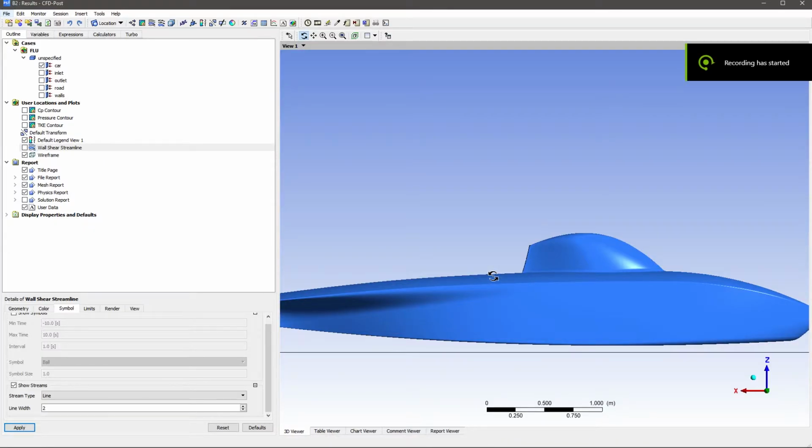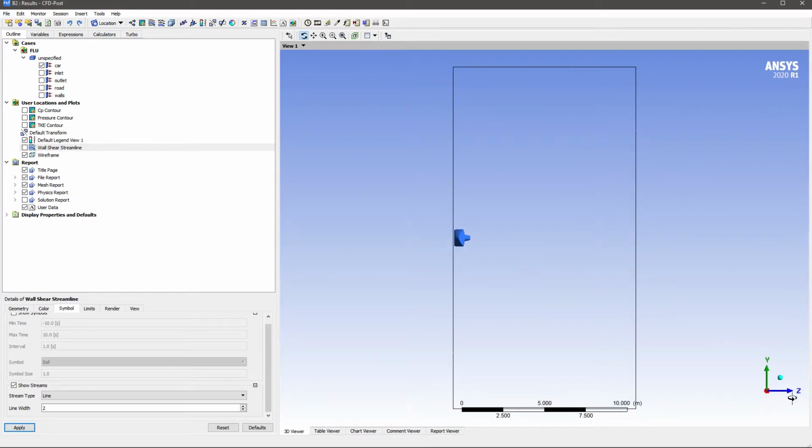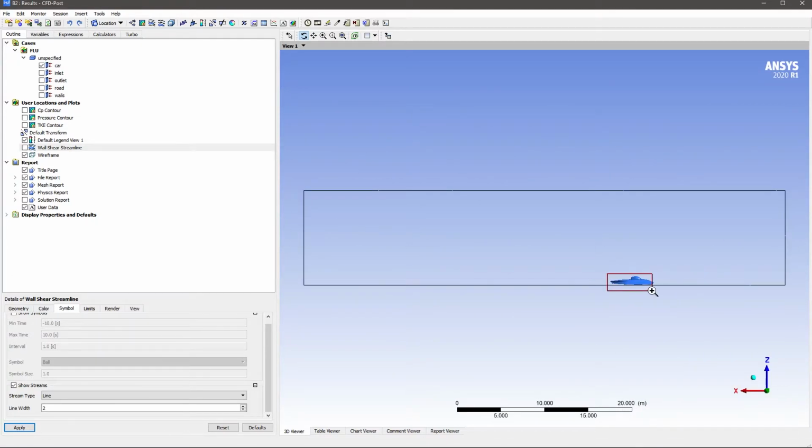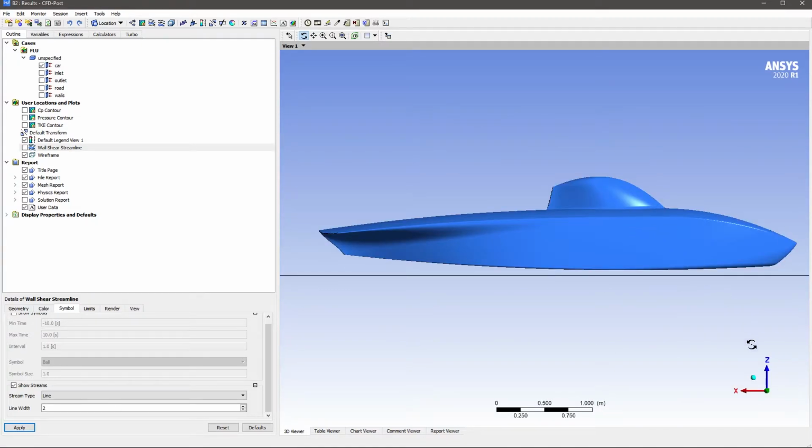All right, so now I'm on the right side of the car and I've just finished taking pictures of all the images for this side. At this point, we're going to try and do the ones for the front and the back. So I'll just do the front as a demonstration and the rear can be left to you guys as an exercise. So here I'll actually start over on that view again. Starting from this view again, be really aware of the coordinate system with the car. At this point, you'd want to click the negative X arrow.